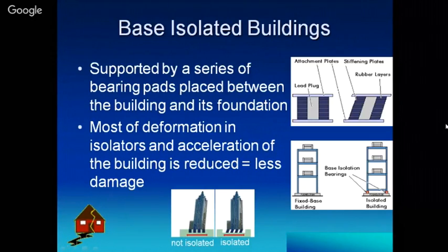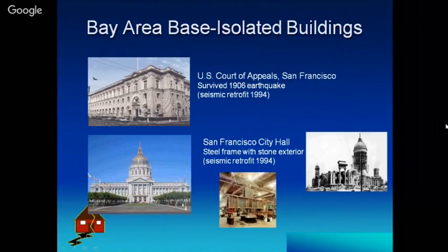And there is also a complete design for that. You need to analyze the forces which are going to come, and accordingly, from whatever company you are taking the bearings, you can give your configuration and your forces, and accordingly place the order. I don't know, it is not very famous in India right now, base isolation, but it is quite famous outside India.